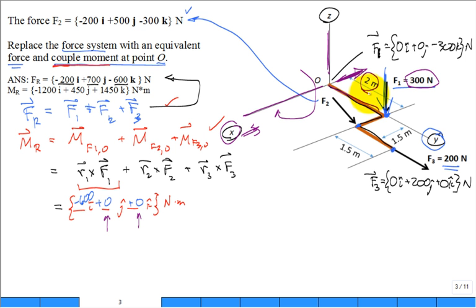So that'll work for a simple force. It'll actually work for this 300 force 3. Do you see that? So let me do this. I know we can set it up in matrix form, but can you get it using kind of a scalar analysis? What is R3 cross F3? What's the moment that the third force induces about the origin?